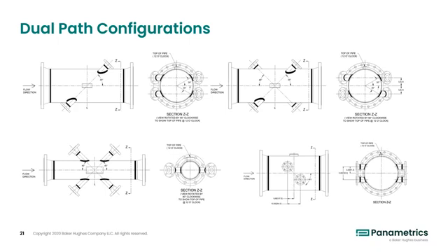Next, adding a second path can assist in cross-flow cancellation due to diurnal effects. As stagnant gas inside the pipe heats up and cools down due to external conditions, such as sunlight or just ambient temperature, the gas can appear to roll or swirl around inside the pipe. Because ultrasonic flows can be measured reliably down to 0.1 feet per second or 0.03 meters per second, this rolling may be registered as a slight positive or negative flow.